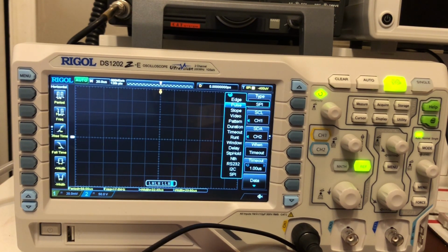It says a signal which reflects the current oscilloscope capture rate can be output from the trigger out connector each time a trigger is generated by the oscilloscope. If this signal is connected to a waveform display device to measure the frequency, the measurement result is equal to the current capture rate. If you press utility, auxiliary out, to select pass or fail, okay, and that's going to be right here.